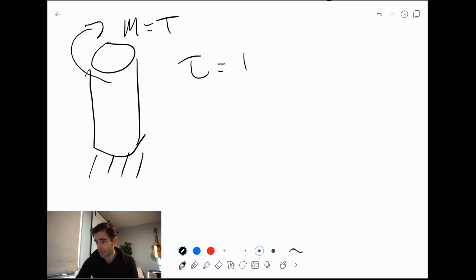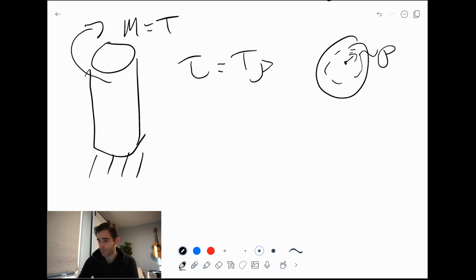And that is going to be this T times rho, which is the distance from the center, same as y in the previous equation. On a circular cross-section, this distance would be rho. But we're going to divide by the polar moment of inertia, J. And again, the polar moment of inertia will change from cross-section to cross-section, and it's important to look that up before starting your problem. So these are four types of stresses: axial, shear, bending, and torsional, that we're going to look at in this video.